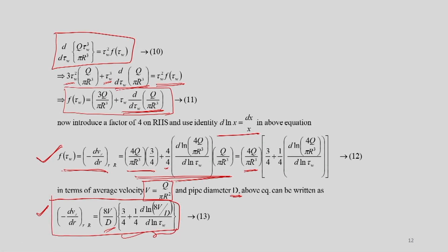Let us say you do the experiment, flow through a capillary, obtain Q versus delta P information, and then if this correction comes out to be close to 1 or equal to 1, then you can say that the fluid is a Newtonian fluid, or if it is not equal to 1, then that fluid is obeying some kind of non-Newtonian behavior. Accordingly, you can get the corrected shear rate, which will give you the true picture of the rheology of the fluid.